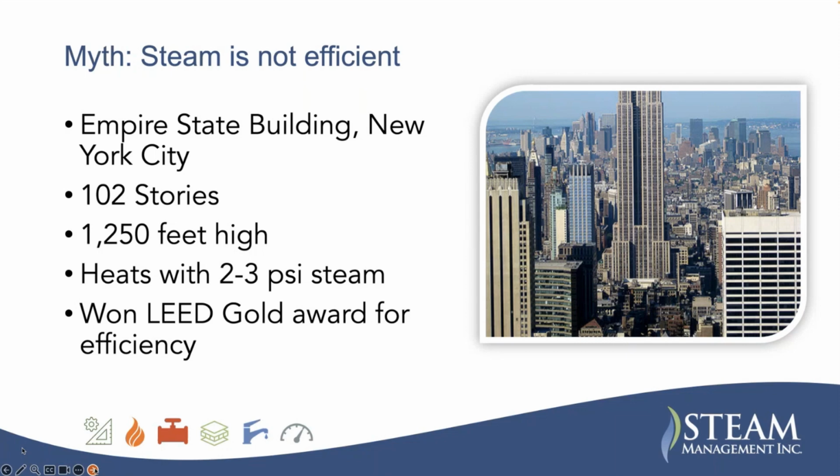Well, steam zooms through a building at speeds of about 50 to 60 miles per hour without using a fan, a compressor, or a pump. It works on steam pressure. And typically, if you're designing a system, for every 100 feet of piping, you'll lose about 2 ounces of steam pressure.